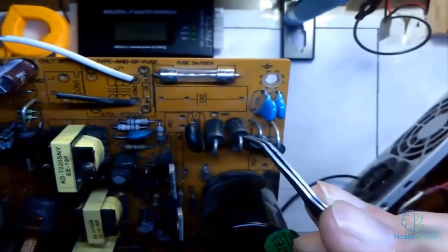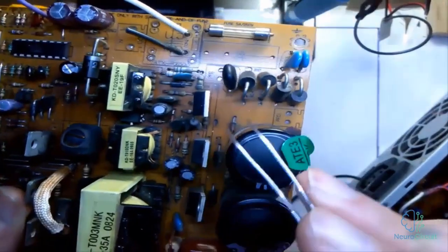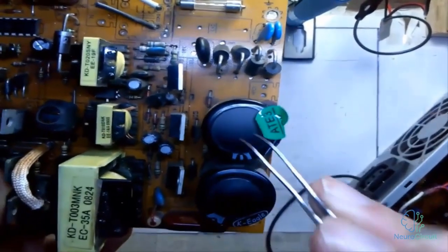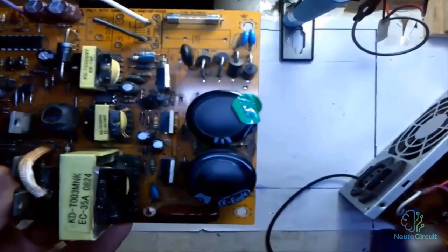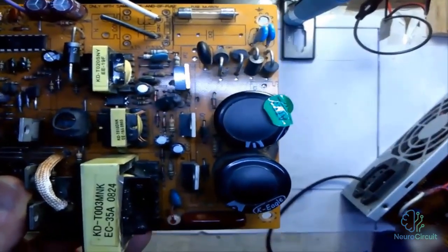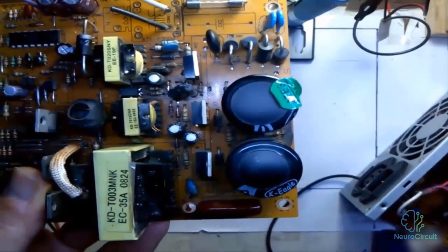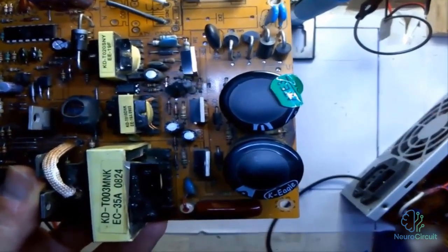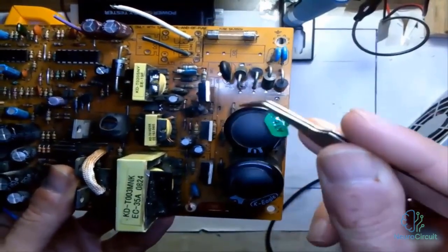After the fuse, there's the bridge rectifier, which you should check, and after the bridge rectifier come the capacitors. The ones that are most likely to fail should be checked. Of course, a faulty capacitor doesn't cause the power supply to not turn on. It just might make the power supply struggle during operation. Whenever you notice that a power supply can't deliver the required power and seems to be struggling while it's running, you can check these capacitors, because they're actually the main components that tend to fail here.